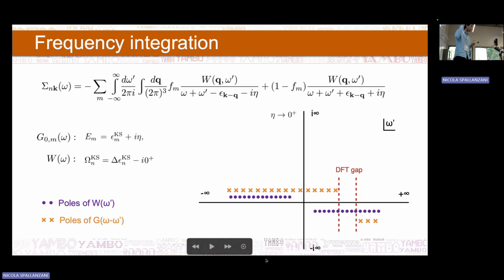As was discussed before, it's a choice you make: you introduce a damping quantity, it's called, and this is a parameter you can control, but you cannot remove, since you don't want these poles to be exactly on the real axis, otherwise you have complications. So to improve the efficiency and to remove numerical problems, you introduce a small imaginary part.